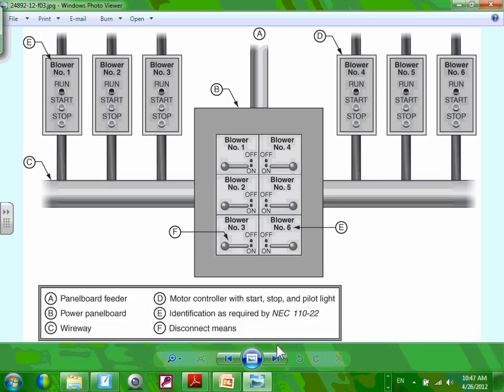Typically, VFD equipment is sized by the manufacturer of the equipment for a couple of reasons, guys. We can't get involved in it. My experience with them is mostly mechanically driven, because they take into consideration whether it is variable torque or constant torque. We don't talk a lot about torque, and electrically speaking we care less what that machine is mechanically doing. Well, I do, but there's a lot of mechanical component in it.